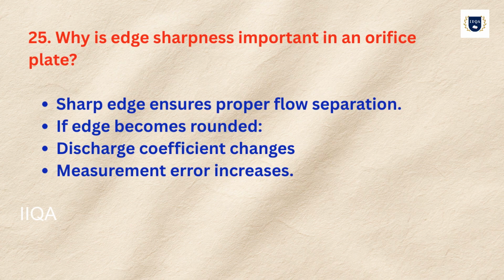Why is edge sharpness important in an orifice plate? Sharp edge ensures proper flow separation. If the edge becomes rounded, discharge coefficient changes, measurement error increases.